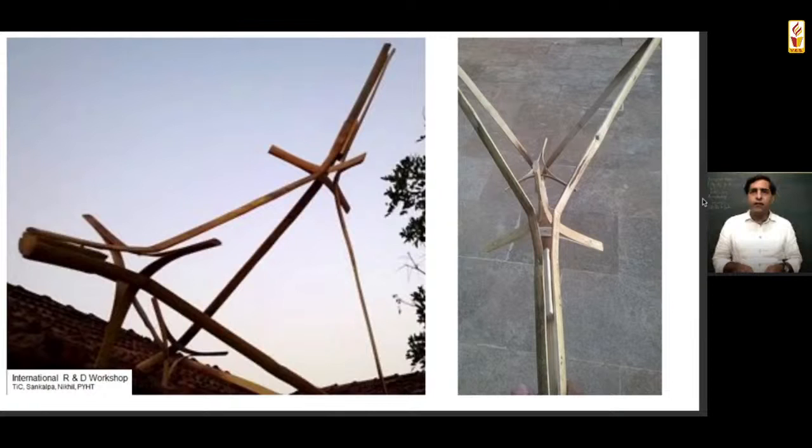If you're using split, then you can very well use the tensile property of the split, and you can create very evocative forms. A lot of work has been done in furniture. One of my areas of interest has been split, because in our country we do not get bamboo which is very uniform in size, which creates a different kind of structural challenge, and more of a construction challenge rather than a structural challenge. Whereas once you go to split, there is a possibility of getting uniform sections.